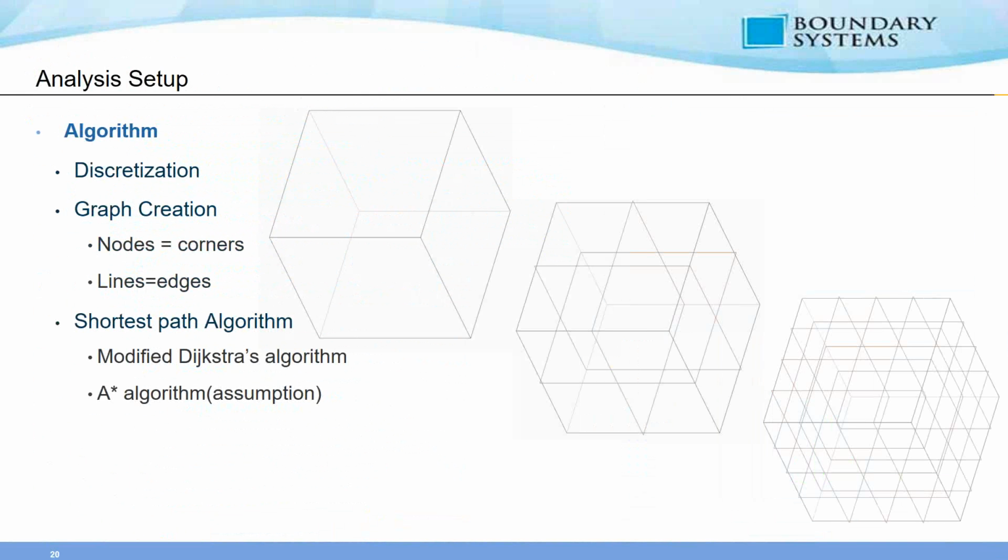The box is then bisected in each direction, yielding 8 cubes. That's the one in the middle. Each cube is then bisected again. It keeps on doing this divisional process until either a box is empty, that is, it does not intersect any surfaces of the model, or the box is less than the mesh size. A smaller mesh size value will yield more accurate approximations of the assembly, but will result in many more boxes and consequently a performance decrease. As I explained, the first box on the left starts off with the entire assembly, and then it divides it up again and again.